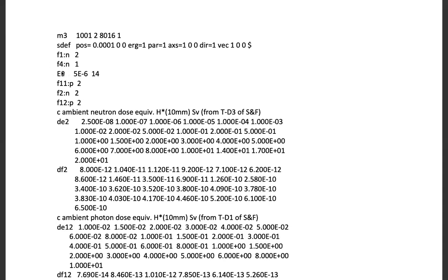So these are the two neutron tallies, the F1 and F4. Then there's also an F2 neutron tally, F2 neutron surface 2. Then for the photons, I've got a tally type 1. Since I've used 1, I'm going to call it F11 for a photon, surface 2. So at surface 2, I'm getting the neutron current and the photon current. Now, in the cell flux, I've got the neutron cell flux in 1. I've got the surface flux of photons on surface 2.